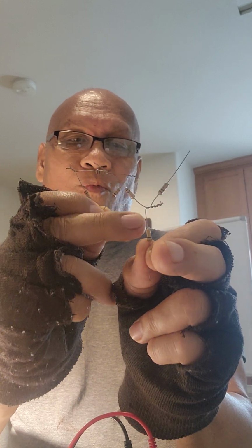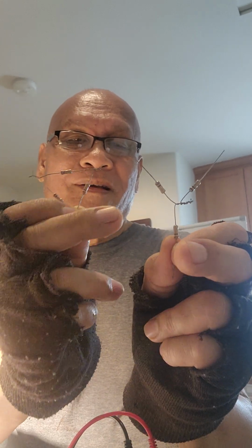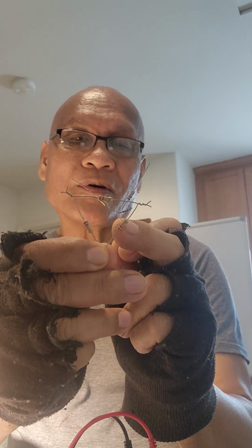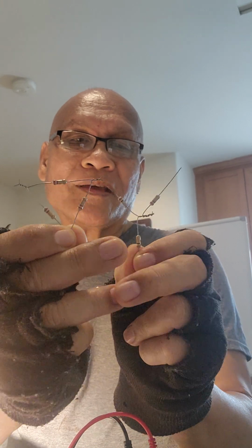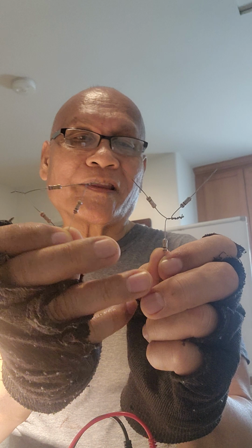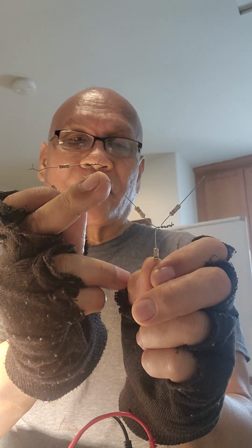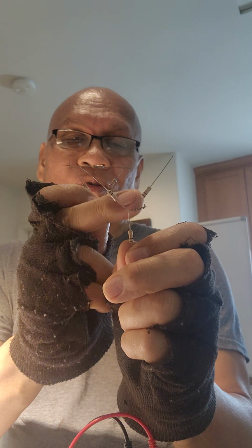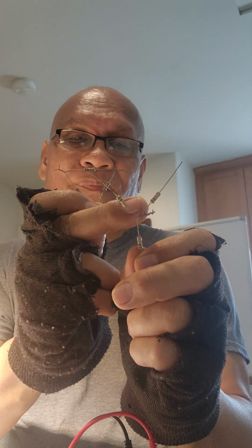And this is 1 ohm, 1 ohm, and 1 ohm. If these are all 1 ohms, the equivalent delta of this will be 3 ohms, 3 ohms, and 3 ohms. And like what I said, to prove that this Y and delta are the same, we measure the resistances between this point and this point, and what comes out is 2 ohms by using our multi-tester.